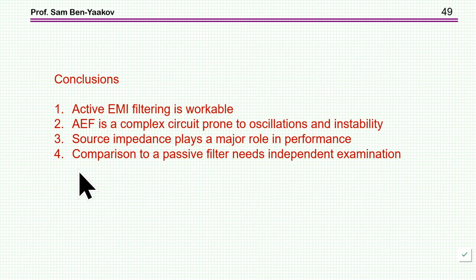And then we understand that the source impedance plays a major role in the performance. So you have to design it for a given input impedance coming from the source. Without that, you'll design it and then you'll put it in the circuit and it might not work properly.